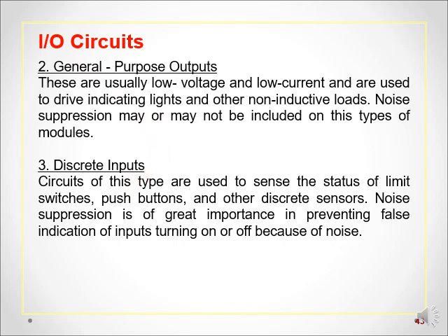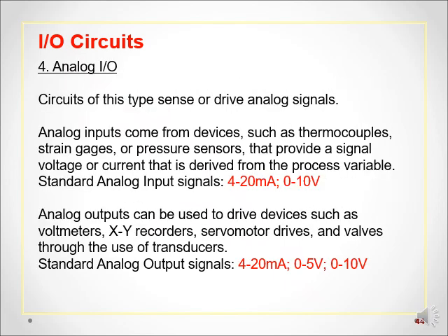Discrete means on-off conditions, so you have only input conditions on and off. You will not have continuous analog input. Some PLCs do support this, but we will not be considering it as part of our syllabus. As I have mentioned, we are not going to discuss analog IOs, but bear in mind, PLCs nowadays can handle analog IOs as well.